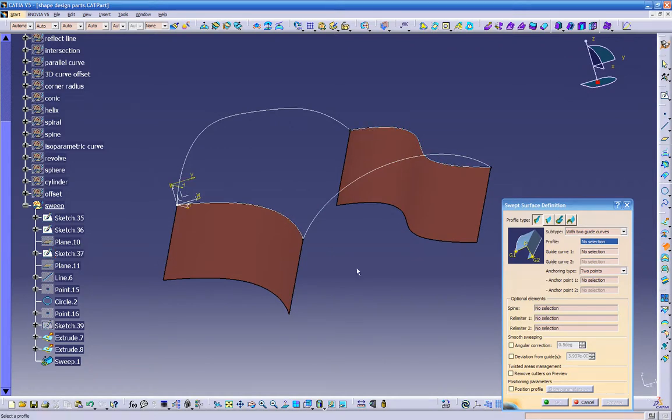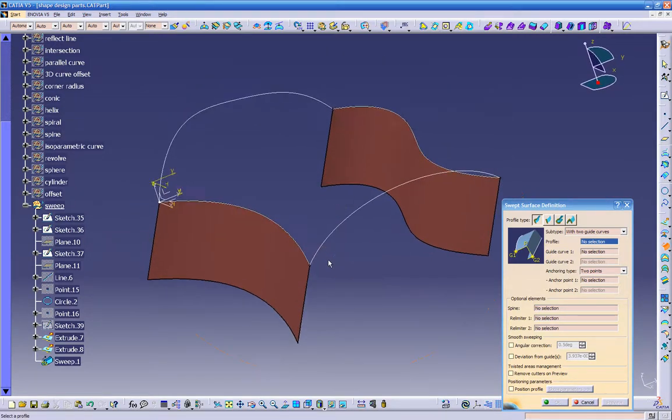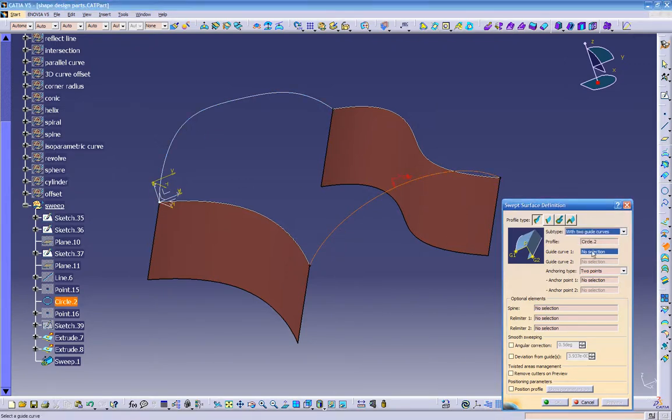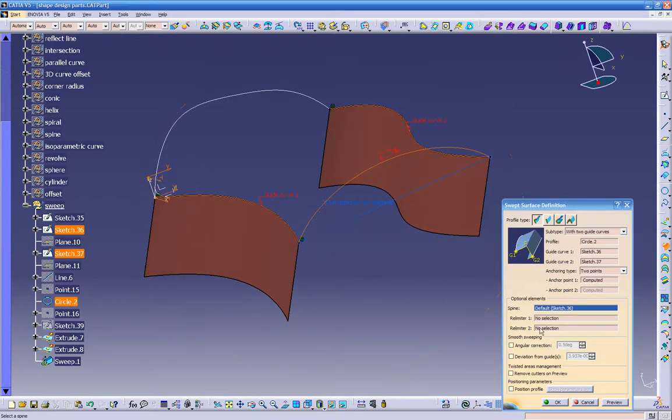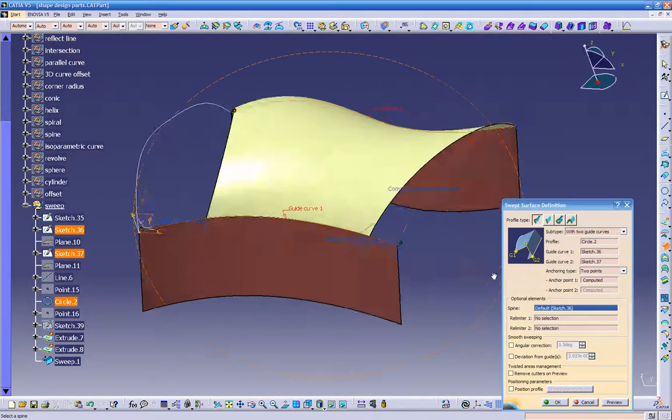It's called a fill surface. We're going to be able to cover this very nice and pretty smooth. But right now, just to get a feeling how the sweeping is working, I just wanted to show you first. Over here it says profile. It's asking us what's the profile that you want us to extrude. So we can click on the profile, this guide or this guide, it doesn't matter. So click on the profile, then it's asking for guide 1 and then guide number 2, which is this line right here. And right now if you do a preview, there's our surface.